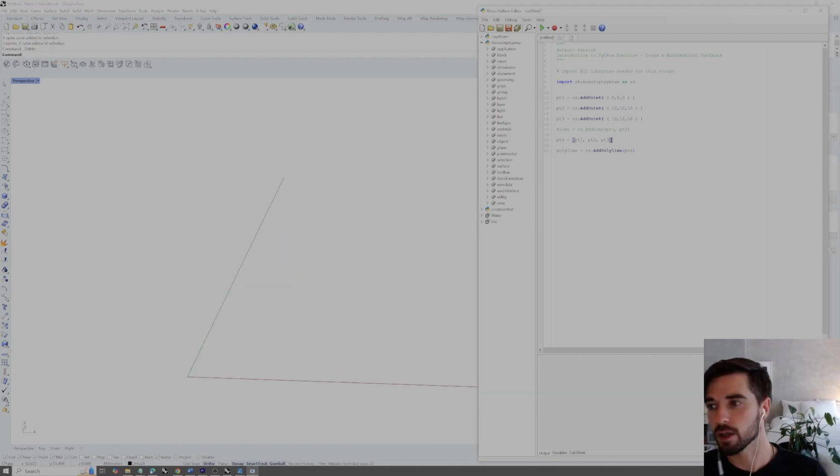If instead of a polyline, we wanted to draw a curve, again, just like in previous videos, we're able to make a curve. So we can set a curve variable, set this equal to the output of a function, and we can set this equal to add curve, open parentheses, and just like a polyline, this takes an input list of points, which we already have called points, so we can feed points in.